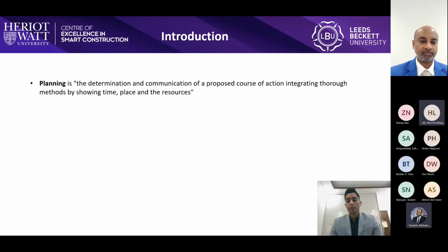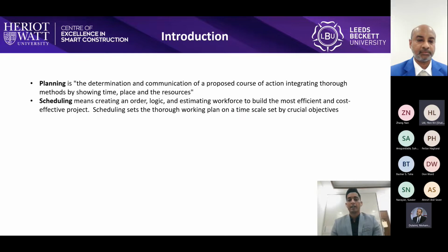Now the topic is planning and scheduling. So let's define what planning is. Planning is the determination and communication of a proposed course of action by integrating thorough methods by showing time, place, and the resources. Basically, it lists all the activities by areas and the strategy of execution. Scheduling means creating an order and logic and estimating the workforce by linking all the activities to each other and by highlighting the critical path or the key milestones on each project. A proper schedule leads to the most efficient and cost-effective project.